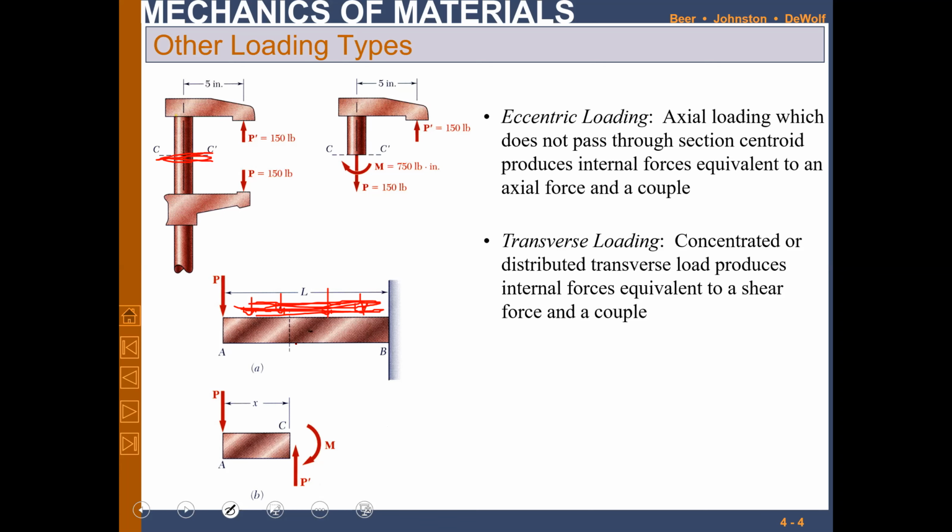And if you take the cross section along this one, there will be equal and opposite transverse forces, that is P. This is equal and opposite, and besides that there will be a moment in this direction. Since the line of action of these two equal and opposite forces is counterclockwise, this moment will be in the clockwise direction, right? But in this chapter we will not be considering this shearing force, because this is along the plane of this section, so this will be the shearing force.